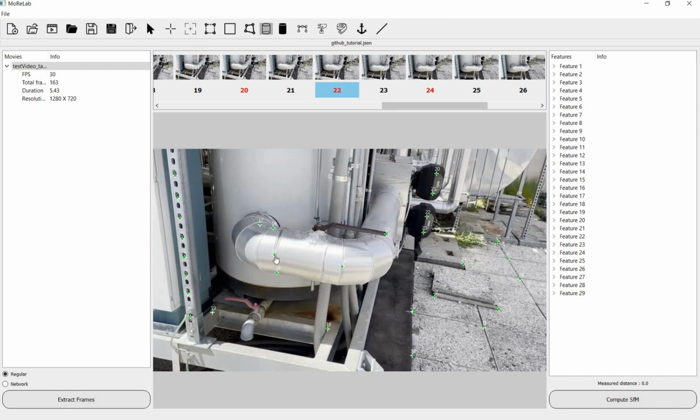So once again I would select the center cylinder tool, and we need to click on 3 points. The first one is the center point, so I click on this point, then the second one is the vertex point, and the third one is the radius point. A circle is estimated for it, and after that I can place it on different 3D points to have a view of the cylinder. I'm providing the depth for the cylinder, and you can see that a cylinder has been estimated.